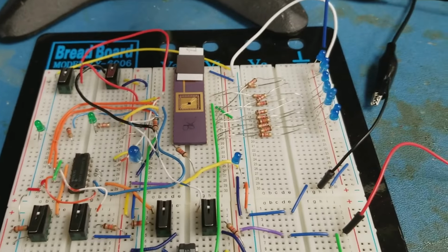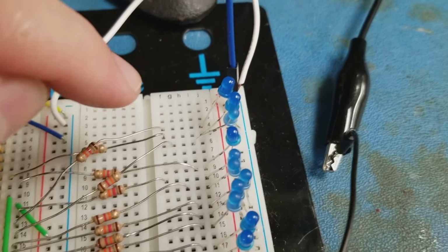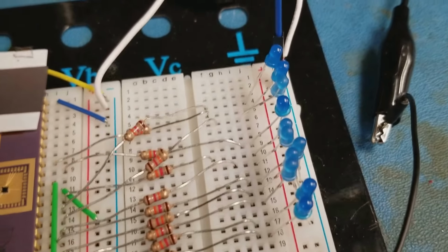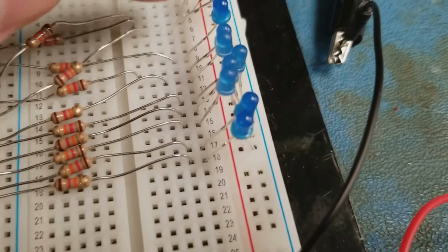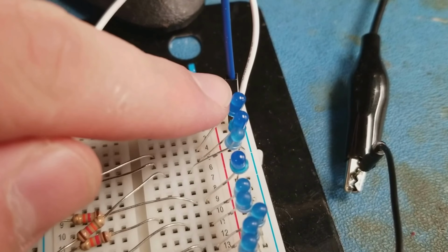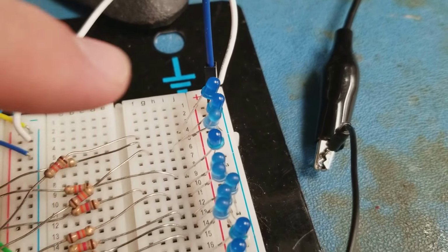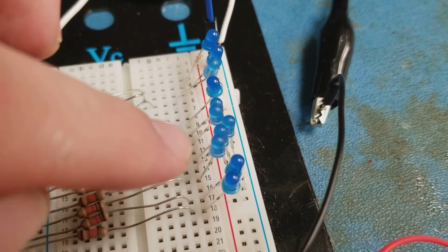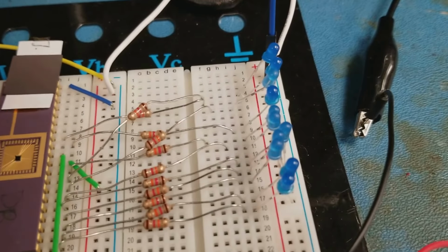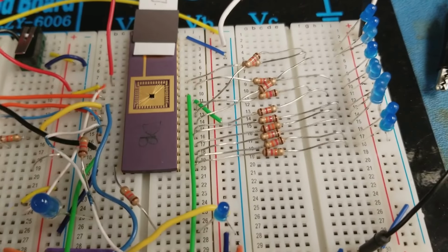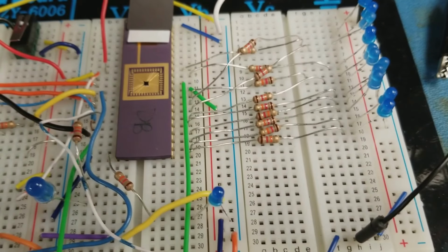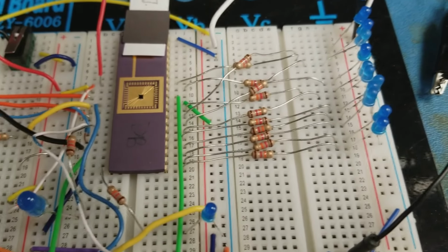So a couple of the other components on here. Up here, these first three LEDs are going to represent the states that are output from the chip. You're going to see a couple, mainly this one will be on generally whenever the game is over. This one will be on whenever it's expecting a button press, and then the other one will come on during startup. These LEDs represent the score. Right now, it's just in binary. One of the things that I'm going to do in the future is change the Verilog code that I used in order to have it output to a 7-segment display natively.